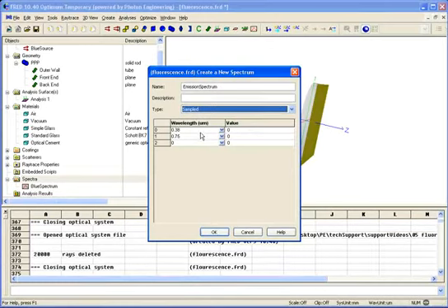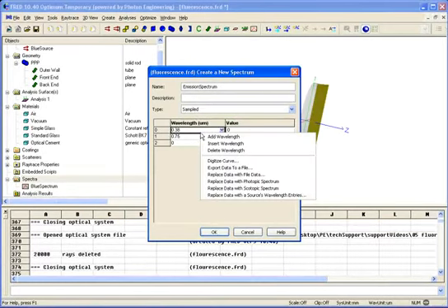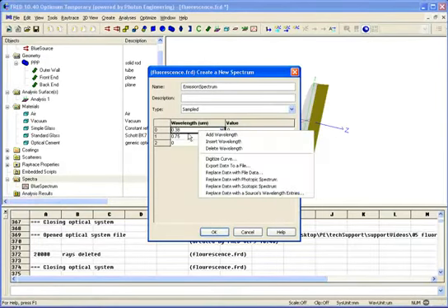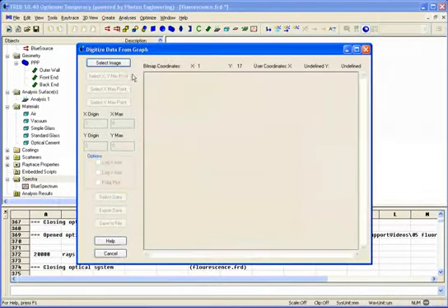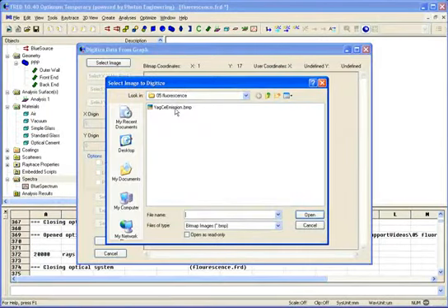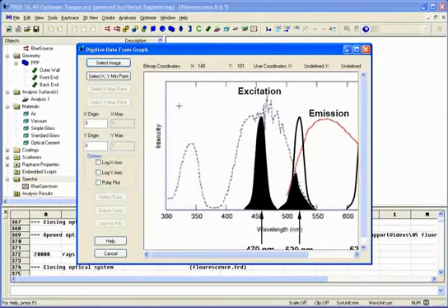In this case now I've grabbed an image from the literature of a particular emission spectrum, and I can go ahead and use FRED's digitizer to pick the wavelength and value pairs out and create this sampled emission spectrum. So if you didn't catch that, it was right-click in the spreadsheet area and do digitize curve. Select an image. I have a BMP of YAG:Ce here, this emission spectrum. Span this out.